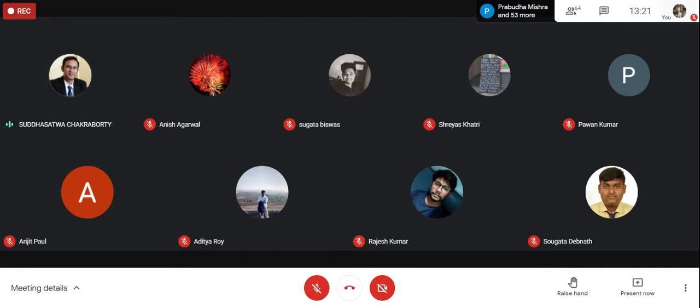So I asked the engineer in charge, my senior, as I was just a graduate engineer, what happened? Why are you putting incandescent bulbs within the stator winding? He said this is a very good way, because mostly during the rainy days there will be chances of moisture contamination within the windings and also the insulation. We all know the insulation resistance values then become very poor. So for that, we need continuous heating.